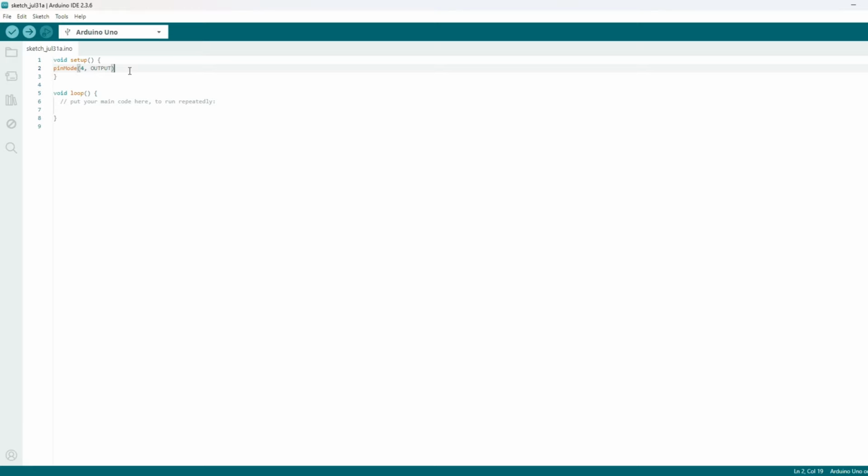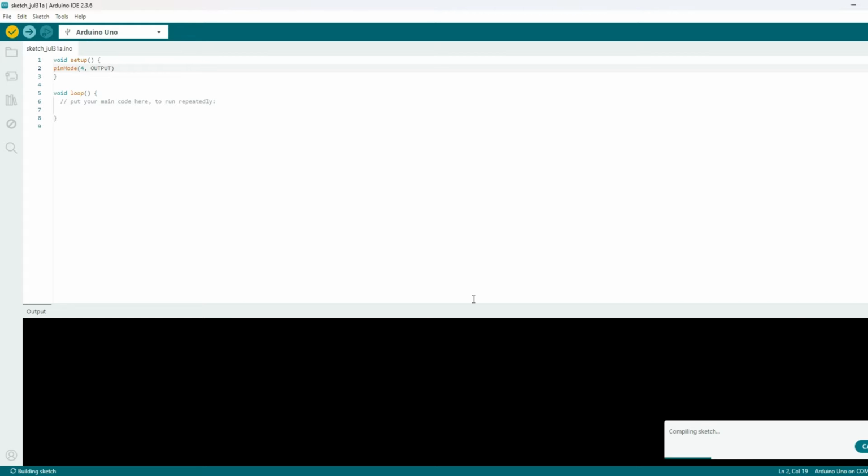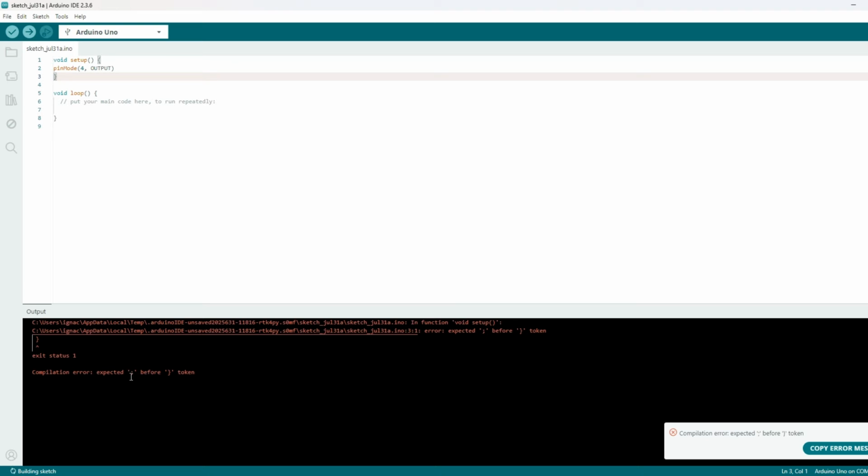Now, very important, this is the most common mistake in Arduino in general. I even make it myself every once in a while, even once per script basically. Semicolon at the end. Every time you write one of these commands, semicolon at the end. If you don't, try and check it, and it's gonna be wrong. Luckily the message is quite descriptive, it says expected semicolon, but you're still probably gonna make this mistake so much. It'll take some time to get it into your head, but anyway.